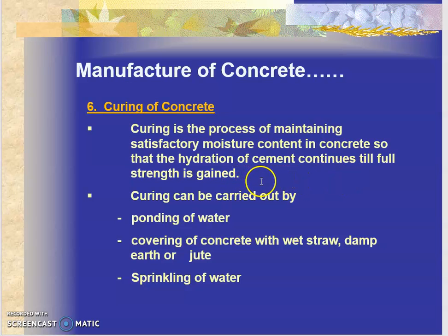Okay, heat will be liberated. You need the surface to be constantly wet. Otherwise, there are cracks which are likely to occur. Okay, curing can be carried out in various ways. You can do ponding with water. You can cover concrete with wet straw or any jute bag, or you can just use sprinkling of water.